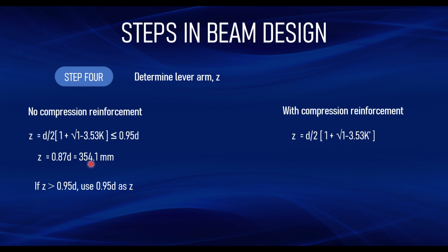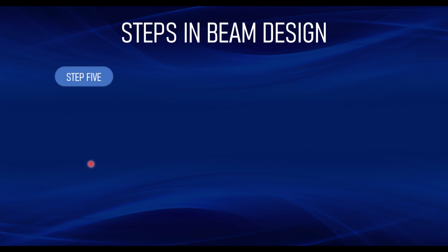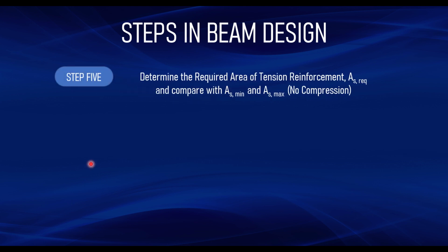354.1 millimeters. So the next thing you have to do is to now determine the area of tension reinforcement. This area of tension reinforcement, you have to compare it with the minimum required reinforcement and the maximum required reinforcement.